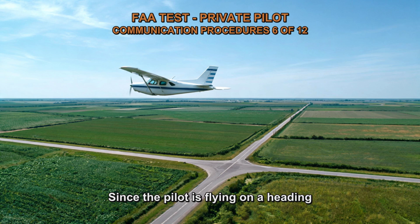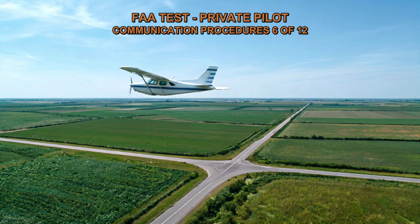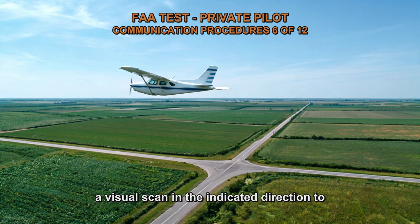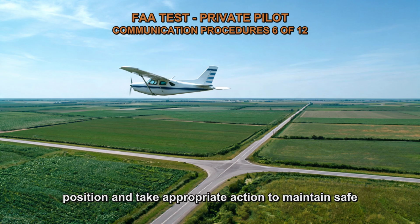Since the pilot is flying on a heading of 360 degrees north, looking towards 10 o'clock would be towards the northwest. Therefore, the pilot should look in the northwest direction to spot the traffic indicated by ATC. It is important for the pilot to maintain a visual scan in the indicated direction to visually acquire and maintain awareness of the traffic's position and take appropriate action to maintain safe separation.